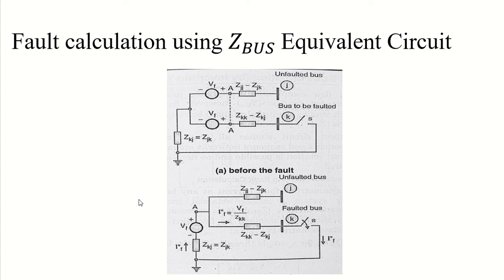But what we will do, we will basically cut off the values of your resistances and form one resistance which will be equivalent to all those resistances, and then we will take the voltage across it, right? So the Thevenin's equivalent circuit will be very helpful for the symmetrical fault analysis, and the ZBUS matrix elements can be used to construct your Thevenin equivalent circuit, the circuit I was just talking about a minute ago, right? So you can find the voltage value between any pair of buses in your network. So we are going to do that.